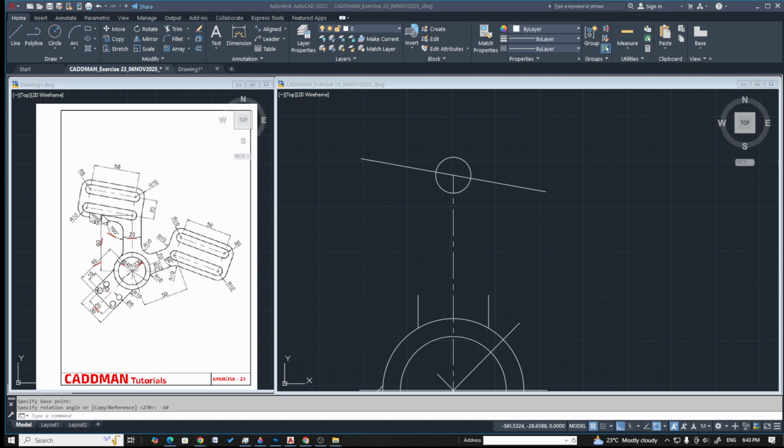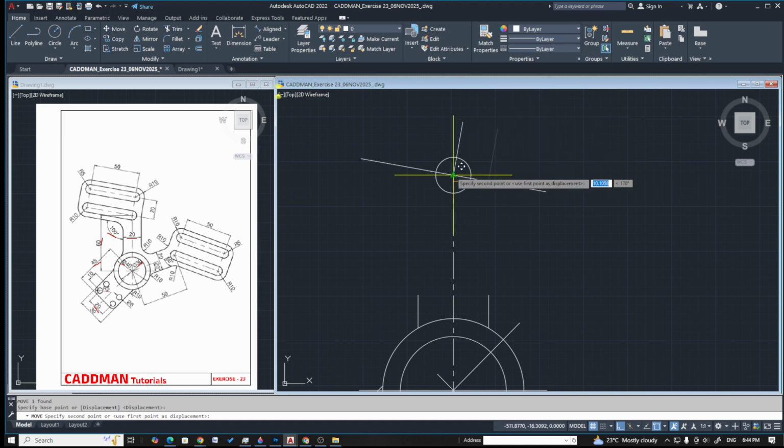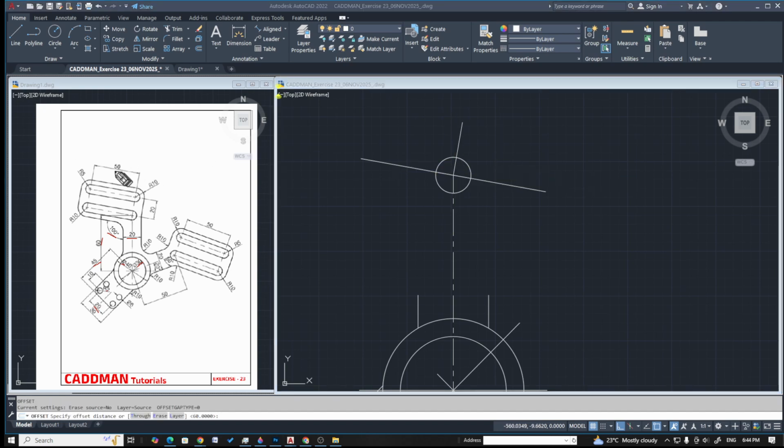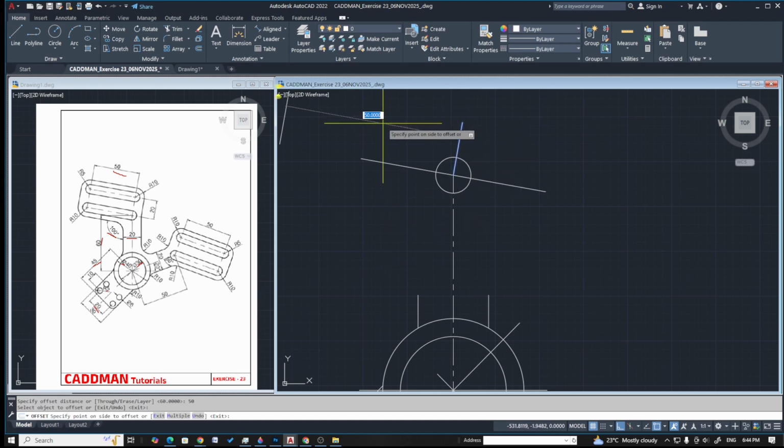and in order to get the other align dimensions of 50 from here to this point, what I try to do is I go for a line command, say perpendicular line to this line. So when I say perpendicular to this line, I'll get a line, just place it somewhere and move the end point to this end point, and from here offset to a distance of 50 in order to get our other two radius 5 center. So offset to 50 from here to here.